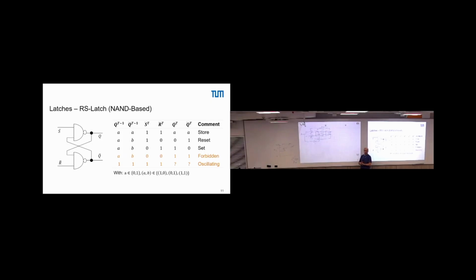So only on this edge, the internal state effectively propagates. And before, it's just stored internally and not sent out. So we send with the rising edge, we have something synchronous. And during this time where we send, we cannot modify the input because it's just blocked by the clock.